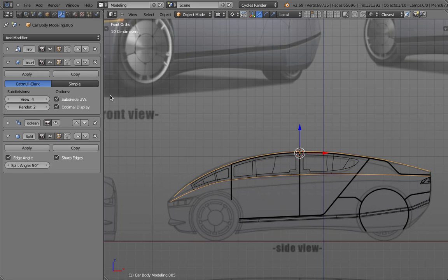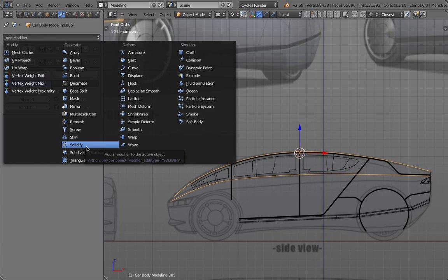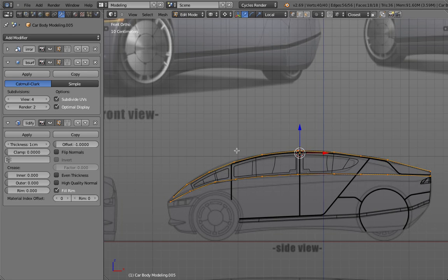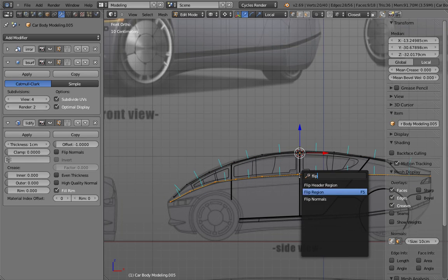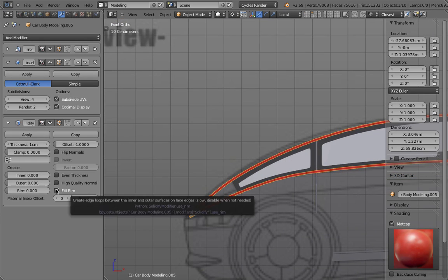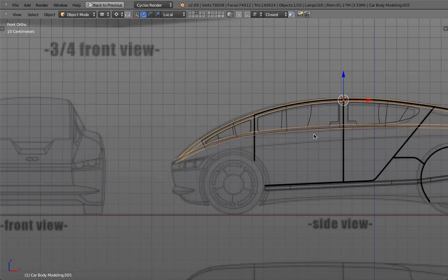If I, for example, give this surface now an offset, so I solidify, I have to adjust the normals because as you can see, the normals are not all organized. Flip those, or like the rim effect to be turned off. And then you see now, the more I increase the value, I can actually make really nice curve offsets into the mirror line.